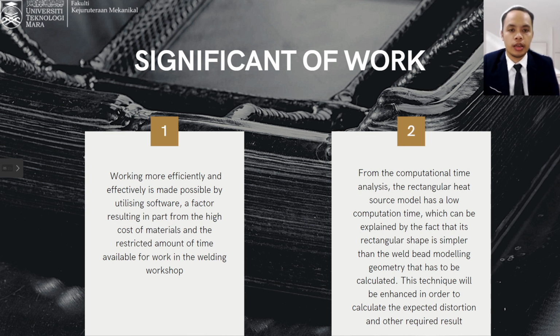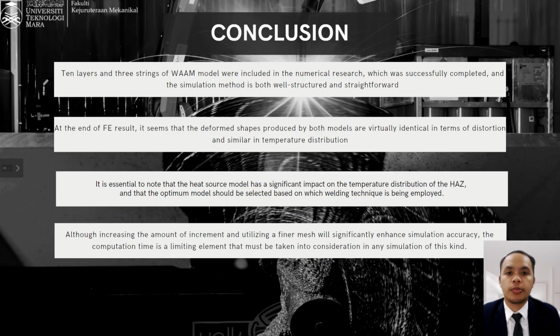In conclusion, it is possible to conclude that the modeling and simulation have been effectively completed using the FEM method. The numerical simulation was carried out with two different heat source models, which are double ellipsoid by Goldak and rectangular, and the following information can be presented as the outcome of this conclusion. First, 10 layers and 3 strings of both models were included in the numerical research, which was successfully completed, and the simulation method is both well structured and straightforward.